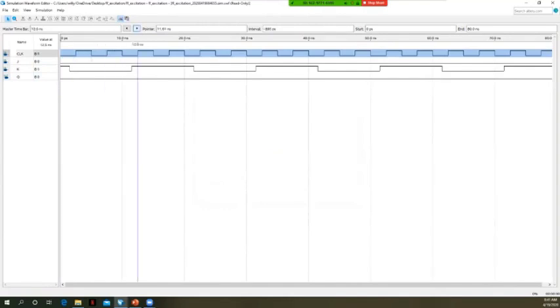When K is a 0 and J is a 1, the output Q should be a 0. So it is a 0. And K will just always reset this to 0. Because in this example, it's either going to hold state or reset it back to 0, Q will be a 0 all the way across here.